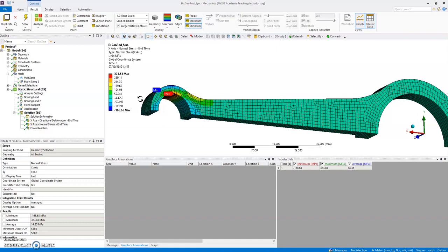Probably too large. Of course, I would need to compare that to the material properties of the steel we have got, and again, that probably would be drop forged, so would have increased strength due to work hardening, but still, be good to compare that later to material properties. Still, can I believe that? Well, it's definitely not 0.83. Okay, 3 to 4, rounding it, and even 3 to 4. I mean, the accuracy I've got on that is absolutely not guaranteed at all.